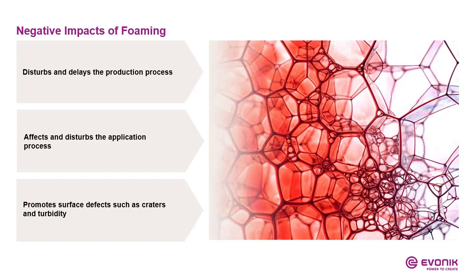Why do we want to avoid the foam? What are the negative impacts of foaming? Because it disturbs and delays the production process. Not only that, it affects and disturbs the application process. And also, it creates surface defects like craters, pinholes, and turbidity.